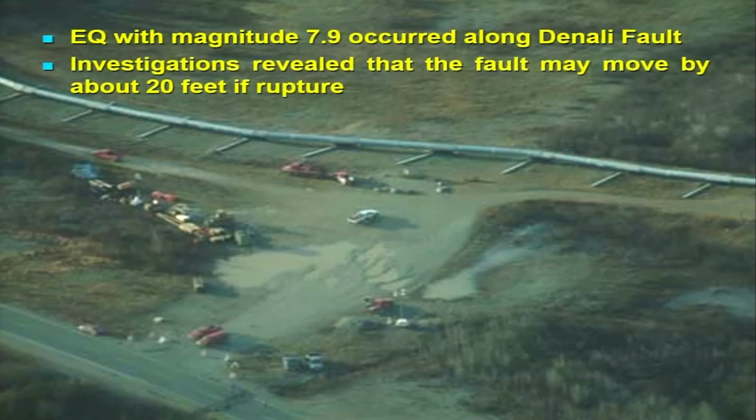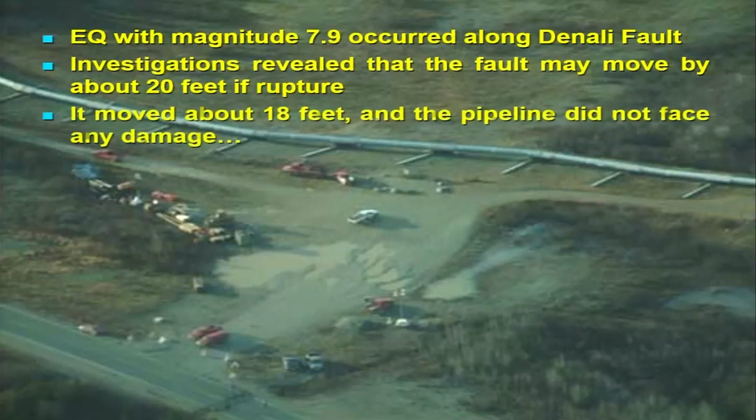So this earthquake was in 2002 along the Denali fault, and the fault is close to the plate boundary between the Pacific and North American plates. Investigation revealed that the fault may move by about 20 feet, and when the earthquake occurred it moved by 18 feet, and the pipeline did not face any problems or damage related to that.